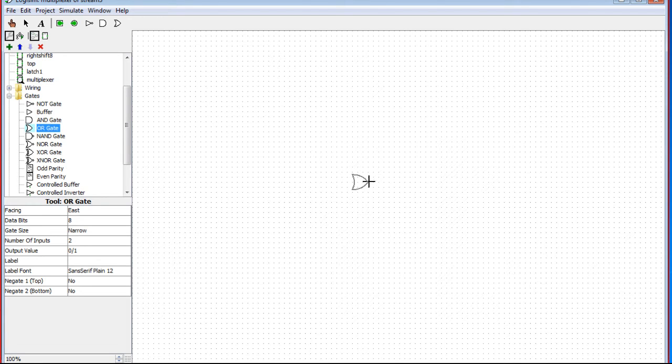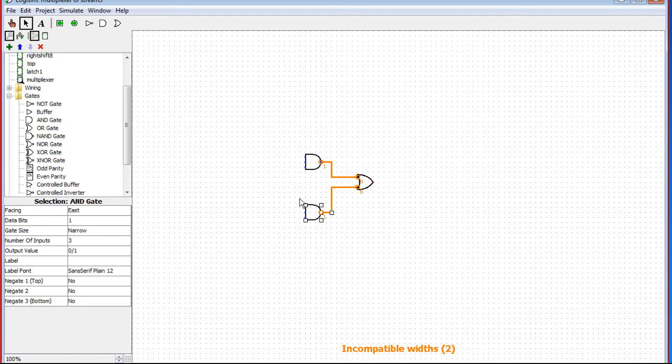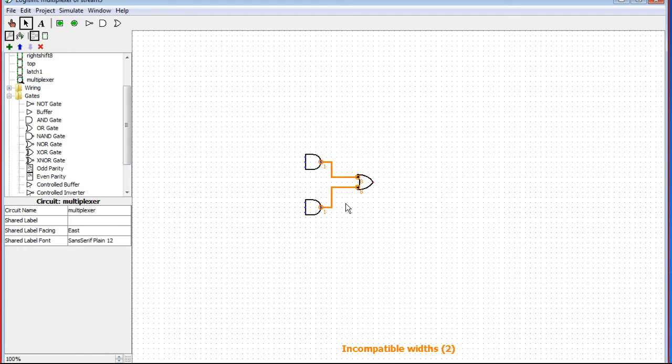Now I'm thinking about it, because multiplexer is just going to use logical operations, and a bit mask just uses logical operations. So yeah, actually, it is exactly like a bit mask. I was going to say something else. I was going to say it's basically going to replace our tri-state buffers that we use to select what goes in. But from a mathematical standpoint, yeah, it's a bit mask.